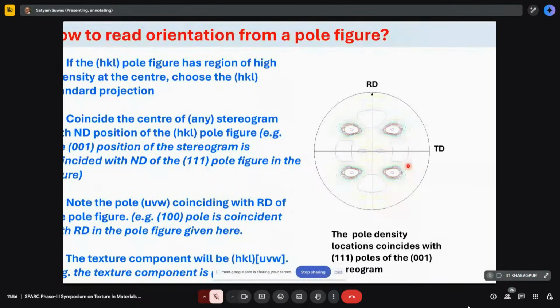So then you have to see where these 111 peaks are located, because if you are doing the 111 plane parallel to the sheet plane, at that Bragg angle you will get only the 111 orientation. This is because of the exclusivity of Bragg's law, because Bragg's law is valid only for a particular plane at one given time, because of the interplanar spacing and Bragg angle constraint.